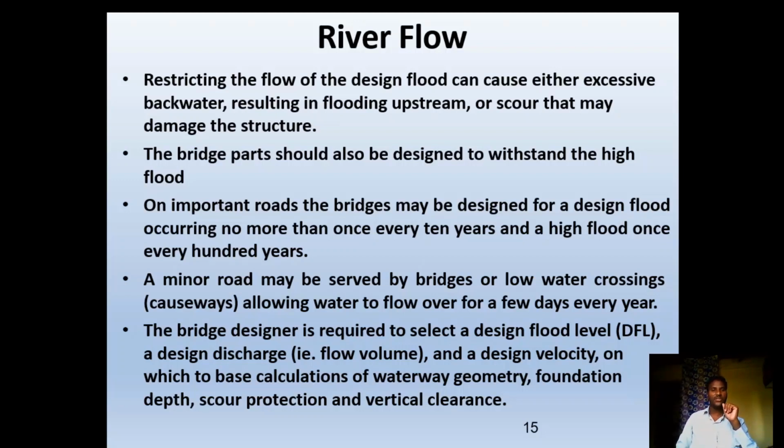The bridge designer is required to select a design flood level, a design discharge, that is flow volume, and a design velocity on which to base calculation of waterway geometry, foundations, depth, scour protection, and vertical clearance.